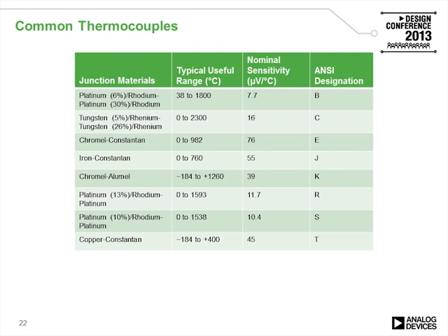They can get out over 2,000 degrees C and go down as low as minus 184 C or below, liquid nitrogen. So they have a very wide range. They have a low output for most of them, and we need to compensate for that. The most popular are the J and K, mostly because they have among the highest output ranges.